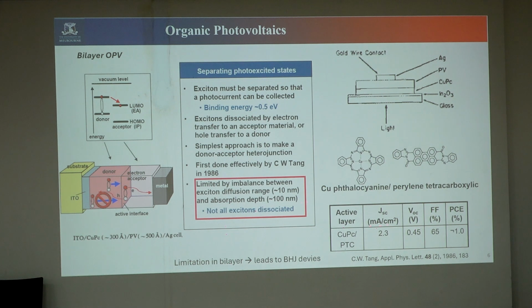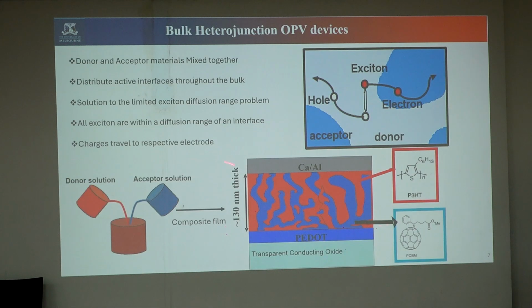How can we do that? That is called this one. Like I said in the morning, instead of making one layer and another layer of N type, we mix both together so that the donor and acceptor phases are very close to each other. Then we coat it, and we get a layer like this. Compared to the previous one, here the donor and acceptor phases are very close nearby. So here is one heterojunction, and here is another junction; many PN junctions will form closely within the layer.